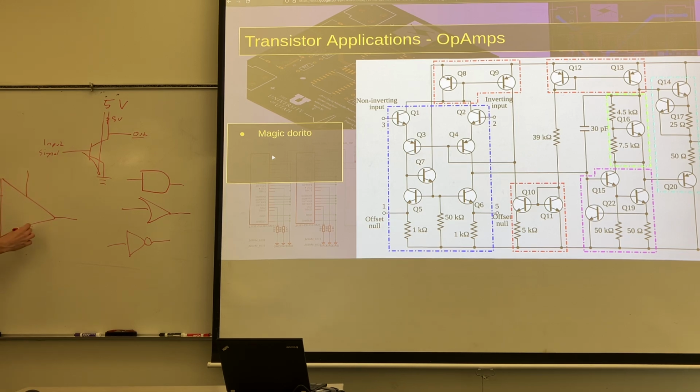But what we'll talk more about next week is, this is basically your positive power supply. You will see it called different things, but what you should take away from that is this is the positive, and this is usually ground, unless you're doing something funky, then it is your negative power supply, usually with the same positive voltage but negative down here.